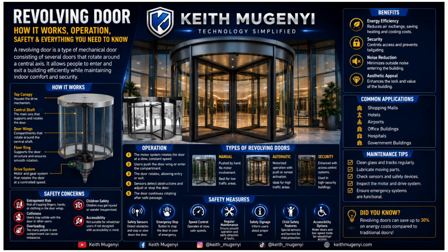Okay, now let's talk about the responsibilities of building management. Firstly, inspect the door daily. Test all the sensors regularly. Clean the glass and floor. Lubricate the moving parts. Check the motor and gearbox. Test the emergency buttons. Inspect the breakout mechanism. Ensure warning signs are available. Train staff on emergency procedures and keep maintenance records.